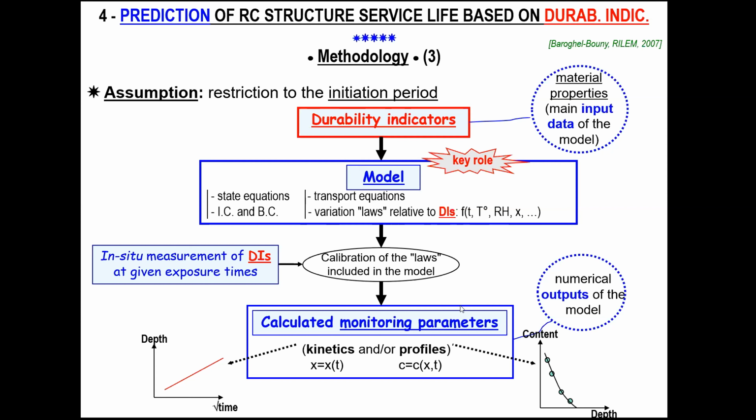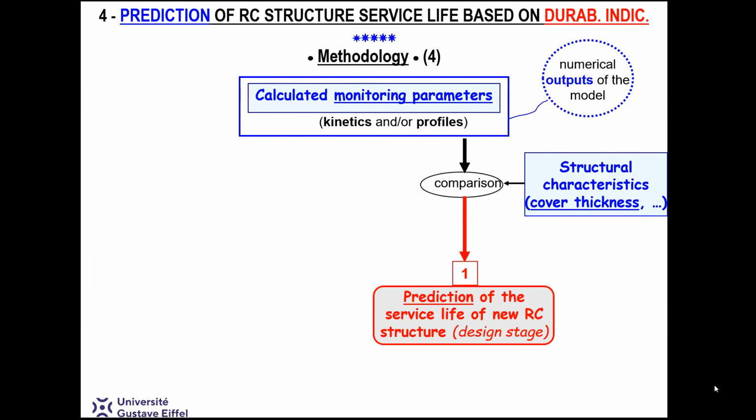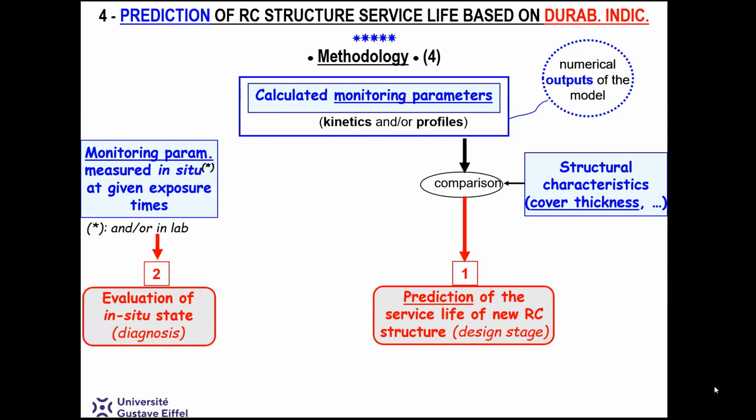When you want to go to durability, you will need to calibrate the model, and you will need to measure the durability indicators at a given exposure time, and then you can calculate what I call the monitoring parameters, and it can be the kinetics of penetration, it can be profiles, and when you want to predict, you will make some prediction thanks to these monitoring parameters.